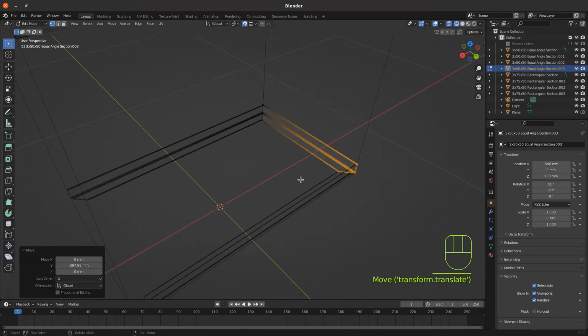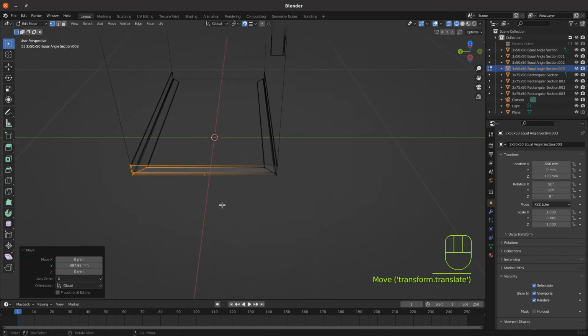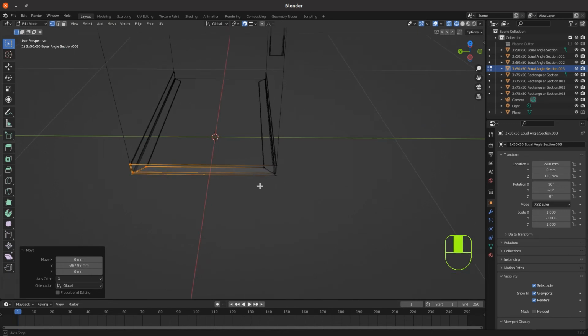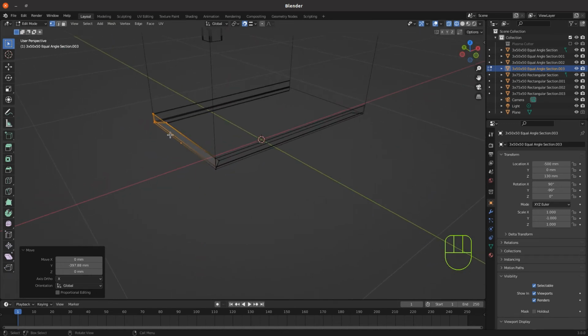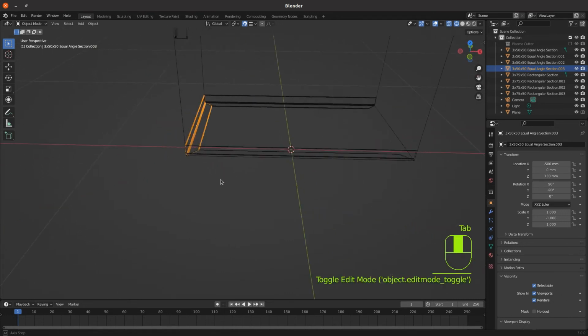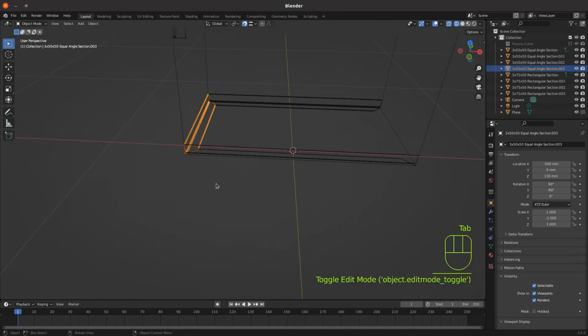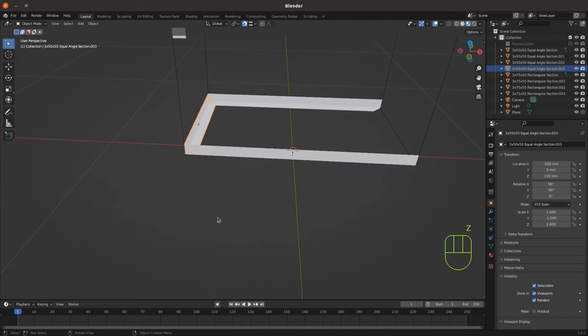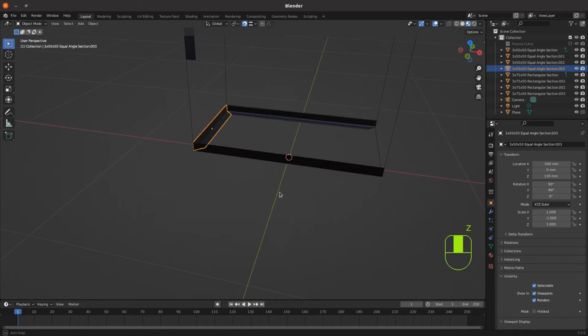It's actually snapped into the right position without going past. So that again gives us the correct size angle iron and mitre for this edge of the bottom frame. So we can tab back into object mode. I'll just press Z and go back into material preview, and we can now mirror that across the bottom and place it on the other edge.